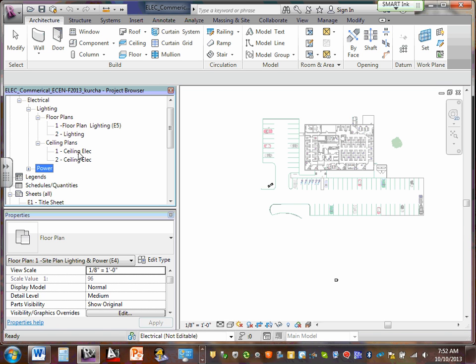Now remember, we brought CAD into Visual. We did the calculation. We got the layout. What's the layout? Where the fixtures are going to be located and which type of fixture. We're going to export it back into CAD and import it into Revit. See the monkeying around they're going to do? You're going to learn it. It's really nice, easy transfer. Now, when we import it to Revit, the layout of the fixtures, when you drop your fixture, the fixture has to be dropped in the ceiling, but circuited in the floor view.